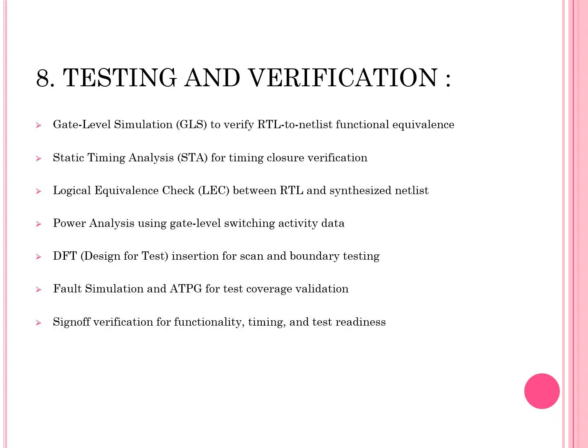This stage focuses on validating the synthesized design to ensure that it functions correctly, meets timing constraints, and is ready for manufacturing. We start with the gate level simulation, which verifies the synthesized netlist behaves the same as the RTL.